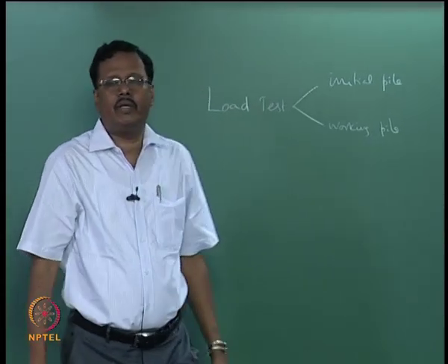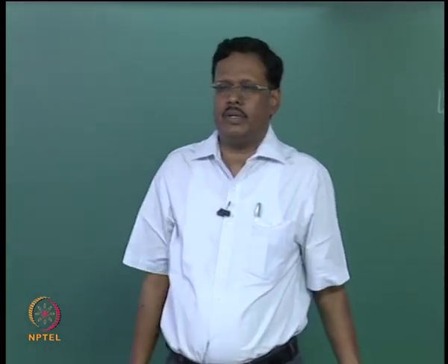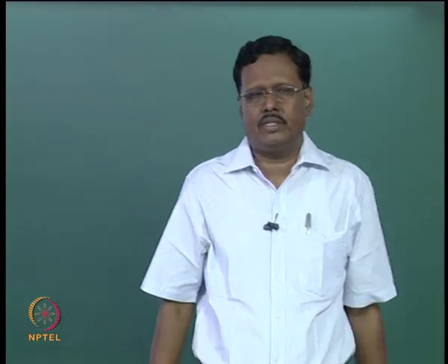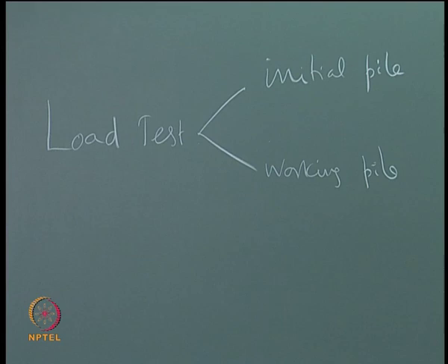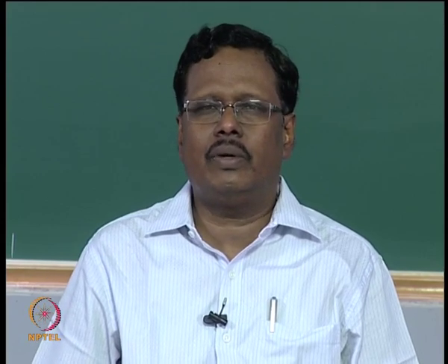So, the initial pile means this pile will be cast separately; it is not part of the structure. You cast the pile, do the test and forget about the pile; it will not be used as a part of the construction. Working pile load test means you will do the test and continue to use the pile for further improvement.